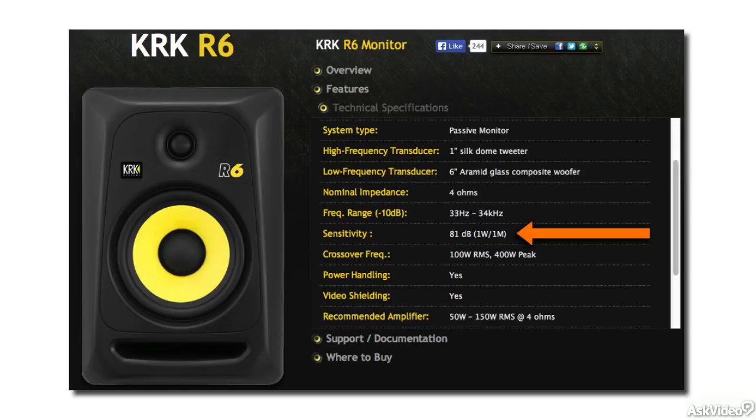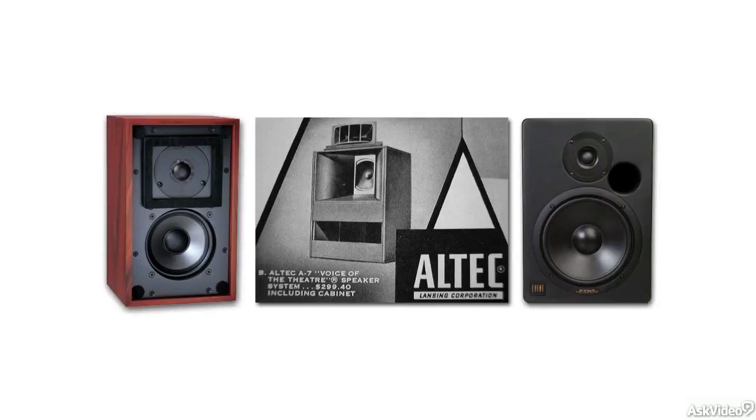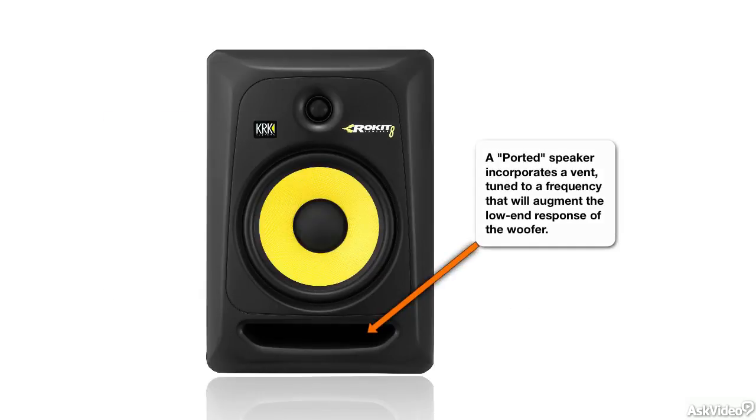Both the efficiency and the low-frequency response of a speaker are affected by the physical design of the cabinet. You may have run into terms like infinite baffle, folded horn, or ported speaker designs. The cabinet can reinforce and extend the bass response of the actual driver, and each of these uses a different approach to do that. Ported designs are popular because they can help to slightly extend the low-end limit without increasing size, but how much help the port provides will depend on placement. Again, more on that next time.